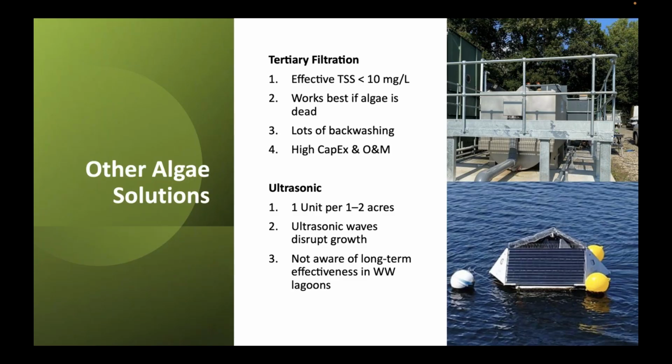The other one you see a lot of is ultrasonic. This unit here in the pictures is from LG Sonic. I've talked to them numerous times. I think it's an interesting technology. It basically uses ultrasonic waves to mitigate the algae growth. However, I haven't seen it be effective in wastewater. I've seen studies in drinking water reservoirs, in lakes and ponds, but I haven't seen it in wastewater, which I think is a little bit of a different animal. So if anybody's done it before and has some success, do let me know. I'd love to have a case study on it, but I can't recommend it because I just don't know its effectiveness.